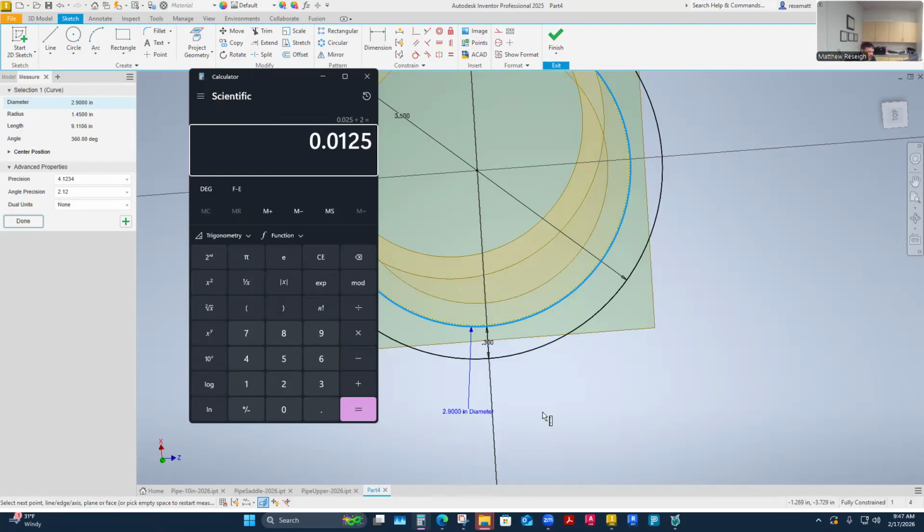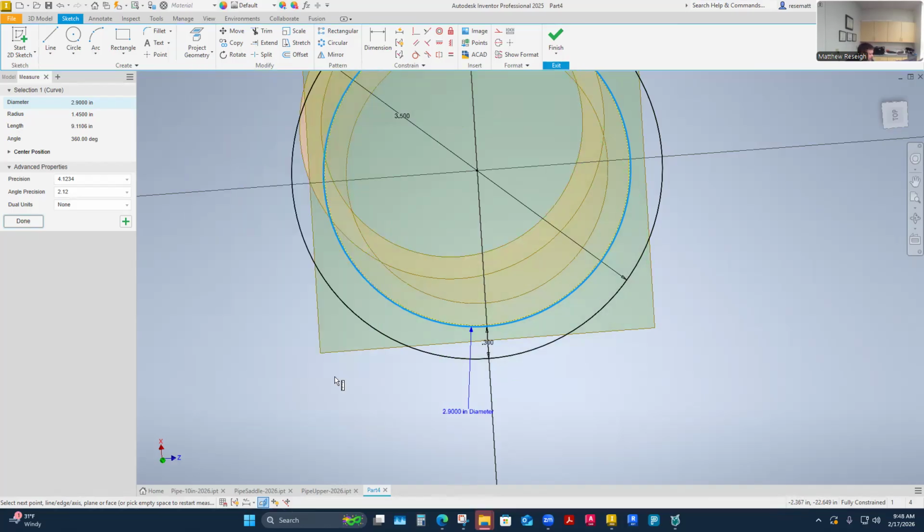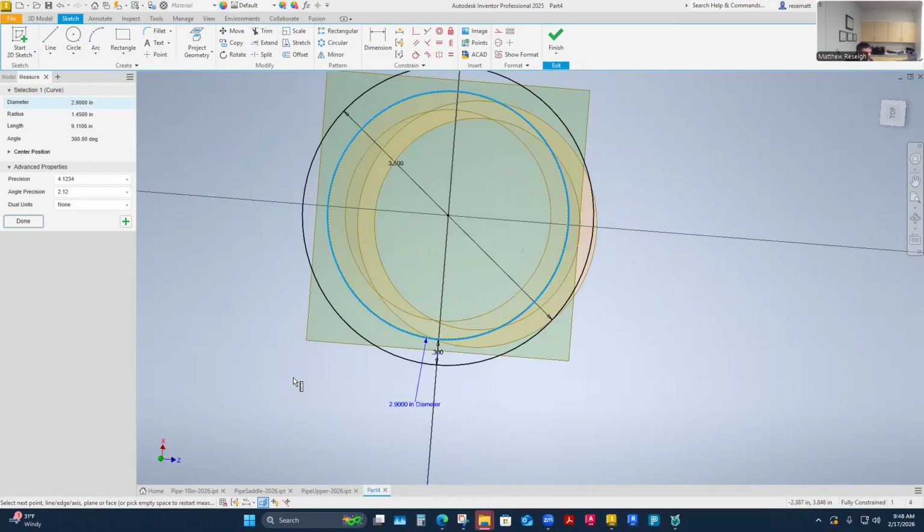You might need to know they're going to weld this with shielded metal arc welding. So they're going to be stick welding this out in the field. Oh yeah, they'll be able to just grab and fill that up. And they would rather it slip together easy than have to fight a fit out there in the field. You just have to have those conversations before you make an ultimate decision, especially where you're a designer, and then your design can kind of affect that if you don't.